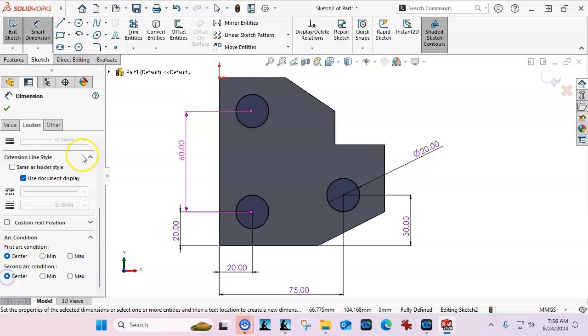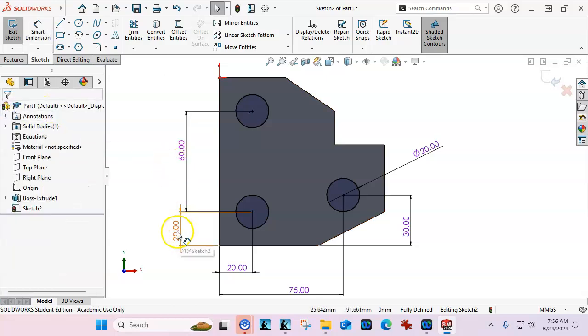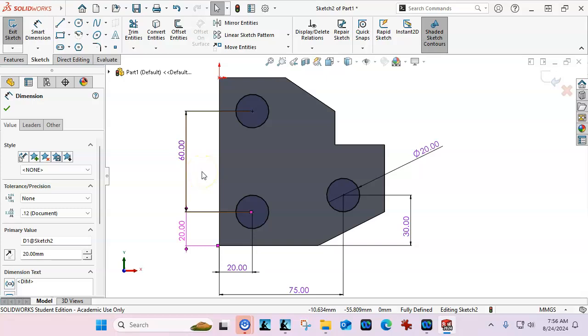Even if you only use those 1 in 100 times on your arc, it is handy to have that min-max. Where that comes into play is I'm given a part that broke and we tried to buy a replacement part, or I want to 3D print it. I take my calipers and I measure between these two circles and I measure the diameters of the circles. I can enter those values directly by going to the min conditions or to the max conditions.